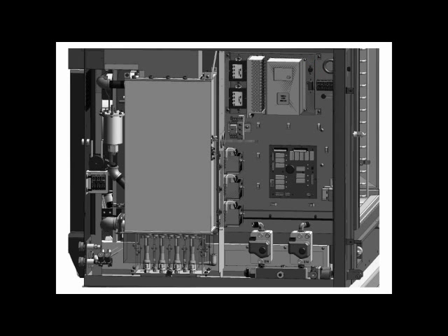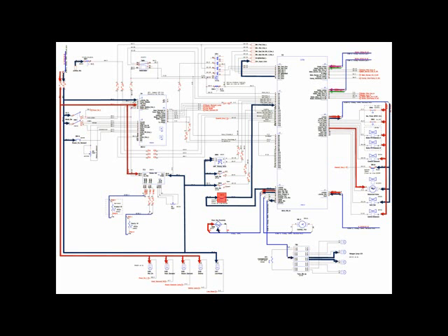The cooling fan thermostat is located to the right of the inverter drive. Here, the switch is closed and it sends negative 24 volts DC to the relay board at J3.8, or junction 3, pin 8.